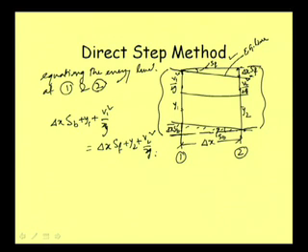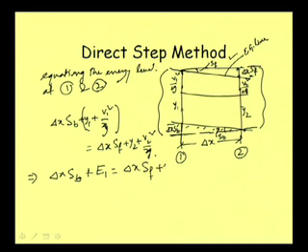Well, now we know that one very popular expression, y1 plus v square by twice g, is nothing but specific energy. So we can write this as delta x into SB plus the specific energy E1 is equal to delta x SF plus the specific energy E2.